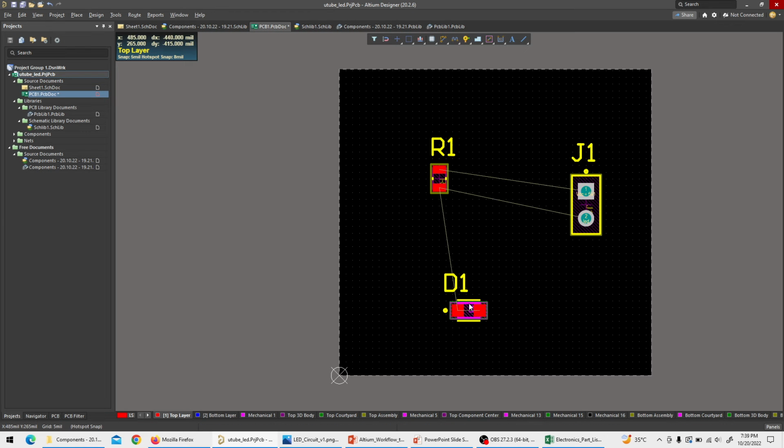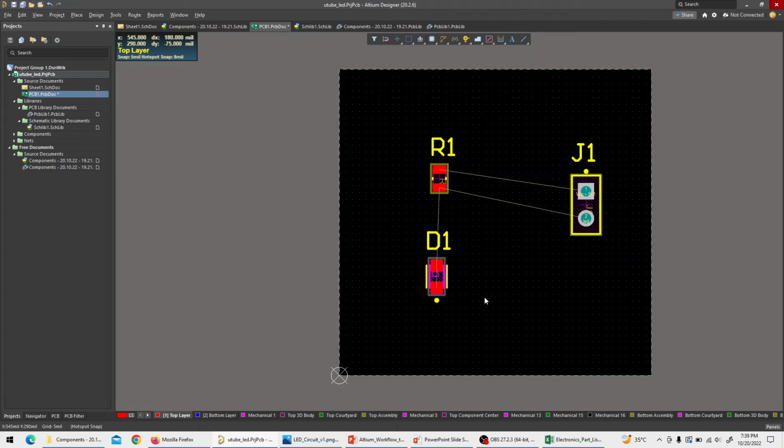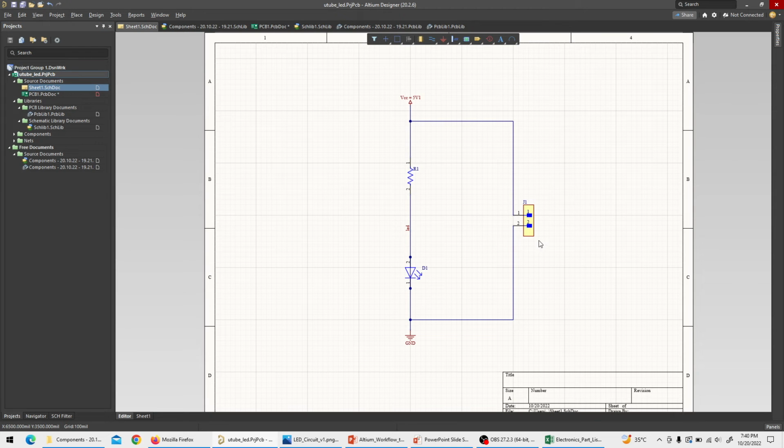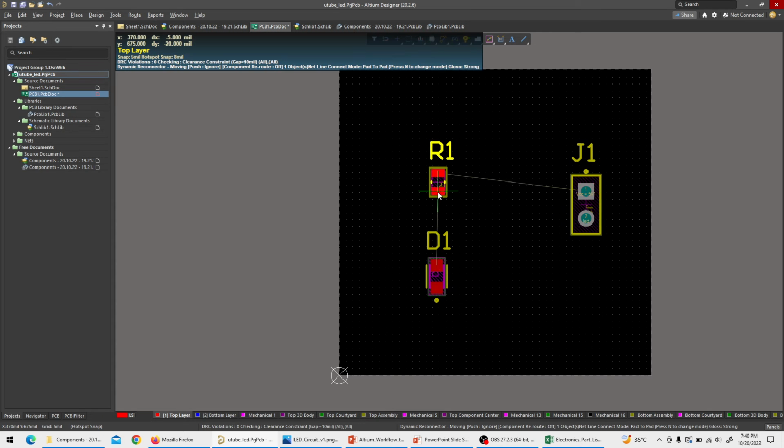All right. And then I'll click my LED, how my LED is connected. Is it like this? No, sorry. In my schematic document, my point 2 is connected to the ground and LED side, and the other one is connected to R. So here's my R, here's my R, and here's my LED.